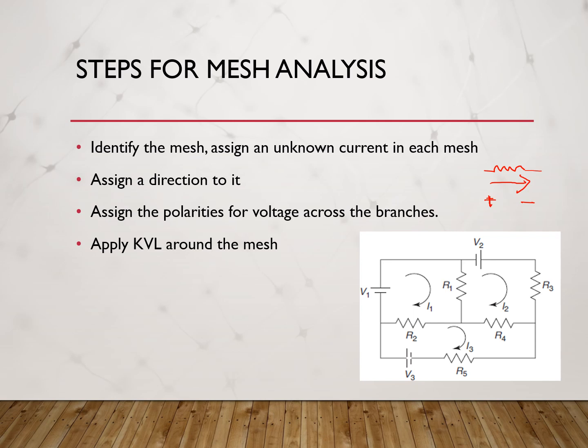Then you apply KVL around the mesh, write the KVL equations, and solve the equations for the unknown mesh currents. So this is basically the procedure for mesh analysis.